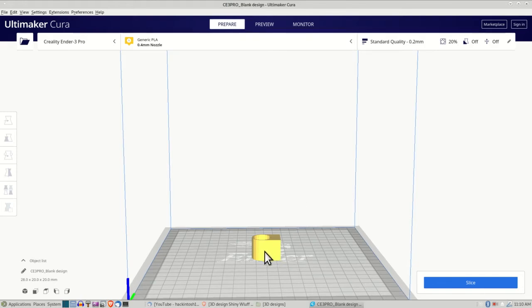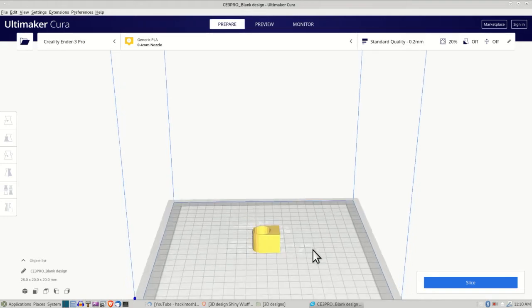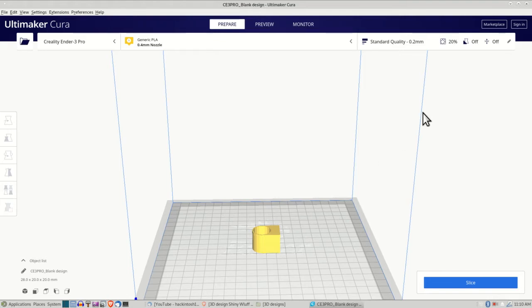You've seen, if you broke apart any plastic parts, inside of it, it's just kind of hollow with lines going back and forth. That's what that infill is. But you don't really have to worry about it. 20% is a good figure. That seems to work rather well. There are times you probably want to increase that.